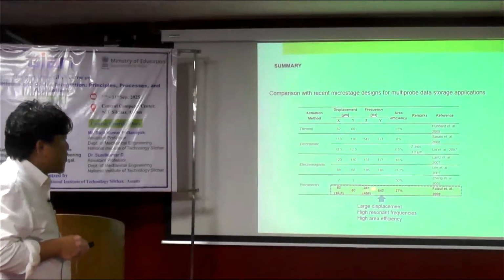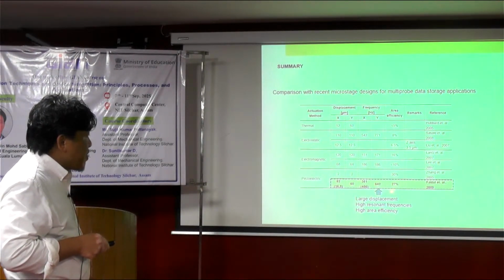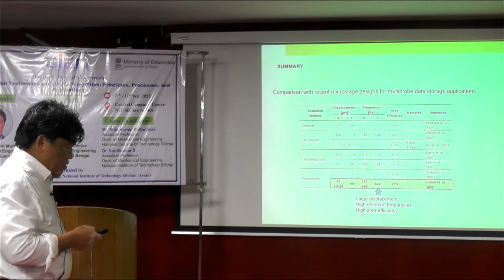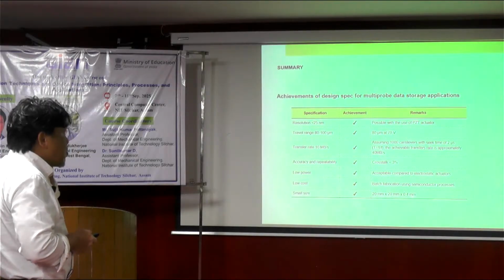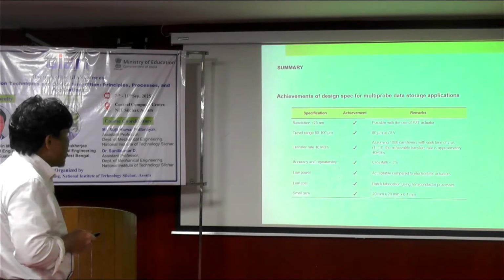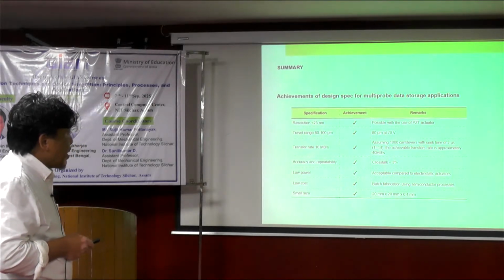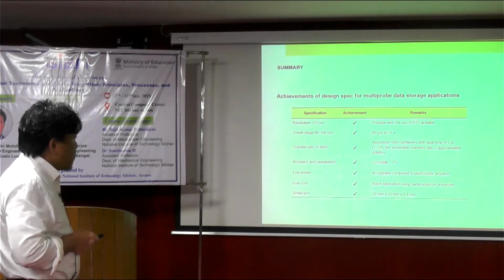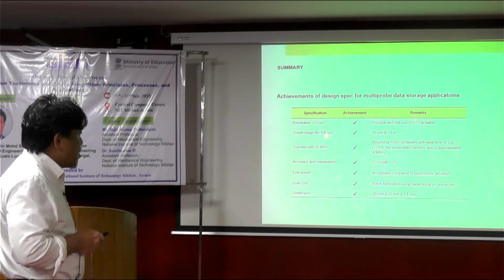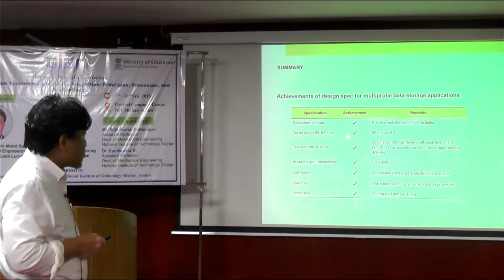And this is the frequency of the system. But here, you can see that area efficiency is much larger in comparison with the rest of the designs. So the achievement of this design is a possible resolution of less than 25 nanometer, because the PZT has very accurate minute displacement, and a travel range of 80 to 100 micrometer might be possible if we use a good actuator design.